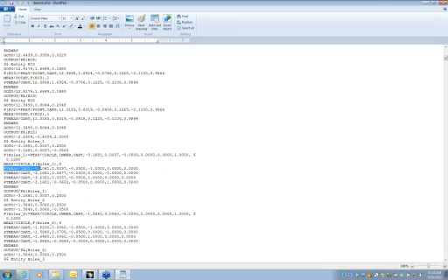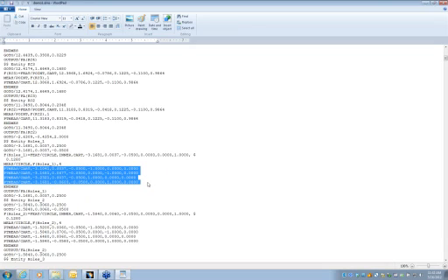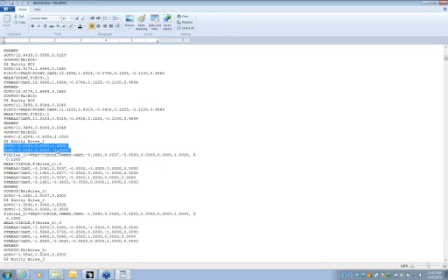Here's your holes. Remember we set it at 4. We went down into 50 thousandths, so it's automatic. Here's all your important approach and retract. It's going to move a quarter inch above the part, and it's going to go down to 50 thousandths. It's going to probe the hole, lift back up, and automatically go over. So it saves you a lot of time in creating a program.